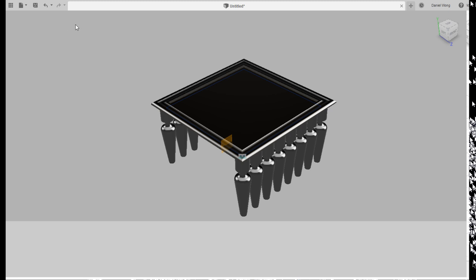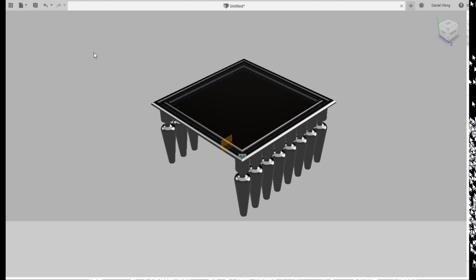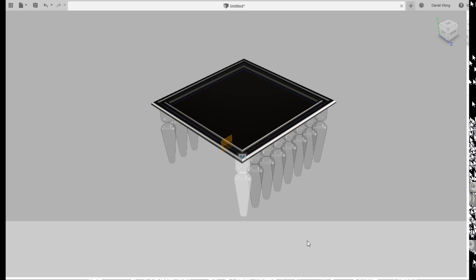And what we can do is change the physical material of what we're working with, right? To do that, it's in here, physical material. And so we can select from a series of materials. So William said we're going glass, we're going glass. And we'll cook my laptop by changing it to transparent anyway. And what we need to do is drag and drop it onto a particular model. So let's say I want to make that leg glass, and all those legs are now glass.